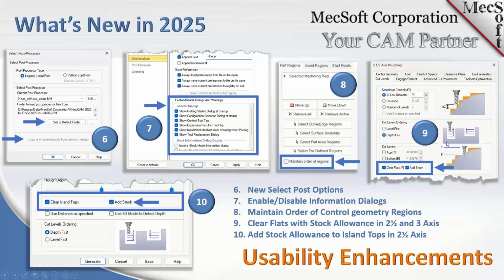So that was maintain order of control geometry. Number 9, we mentioned this about the clear flats and the add stock. We've already talked about that. Number 10, add stock allowance to island tops. This is similar to the add stock in 3-axis, but this is in the 2-axis methods where you have the clear island tops option. So you can add the stock there as well.